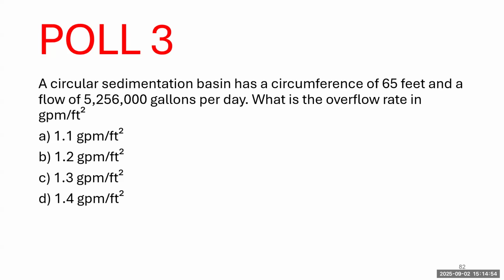Now we have a poll here. A circular sedimentation basin has a circumference of 65 feet and a flow of 5,256,000 gallons per day. What is the overflow rate in gallons per minute per square foot?